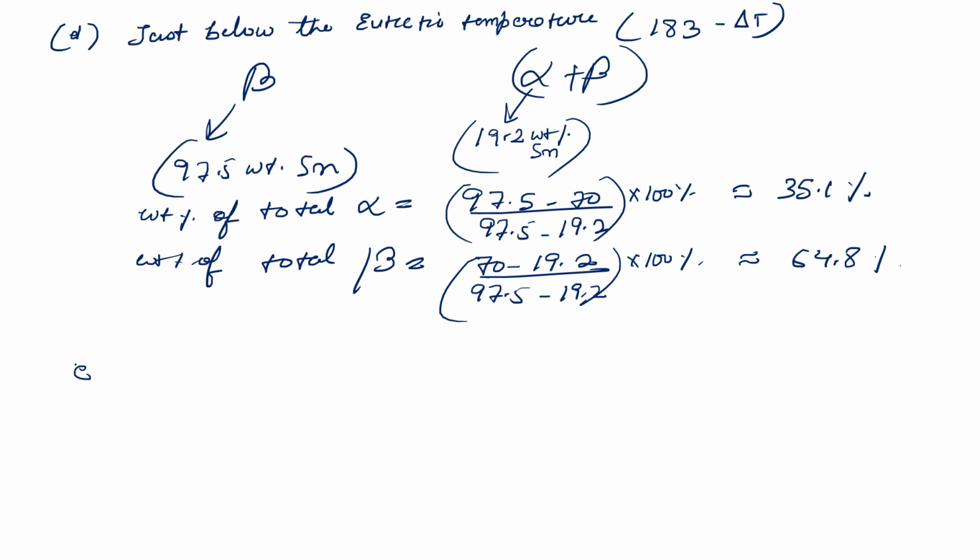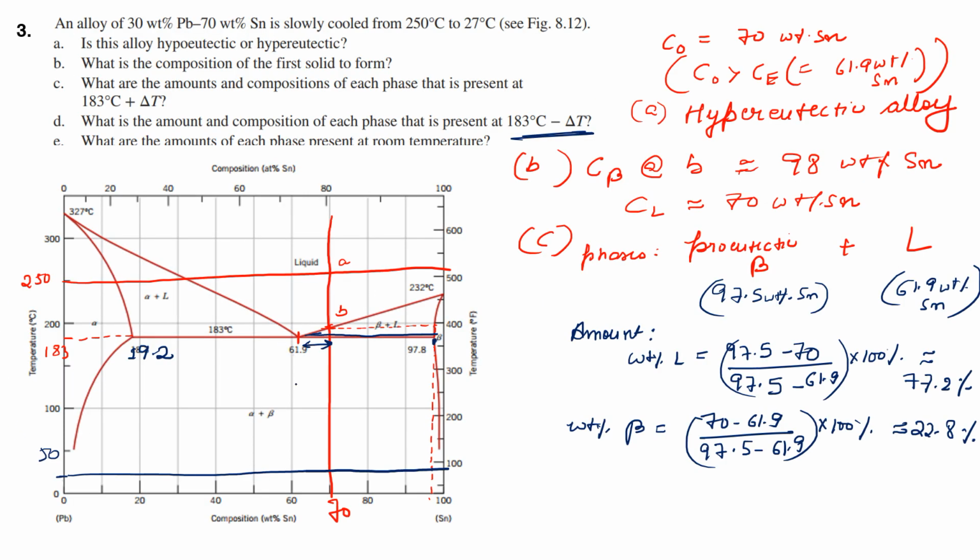So as the alloy is cooled below the eutectic temperature, we can see from here that the tin content in the alpha phase is getting leaner in tin, right? Because the solvus is going this way, my C alpha is going leftwards, that is leaner in tin. And the lead content in the beta phase, both of them are actually reducing, right? Because as I go down, my tin concentration in beta is increasing, and my lead concentration in beta is decreasing this way.